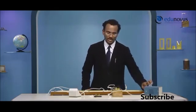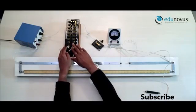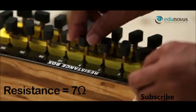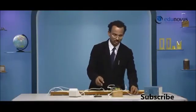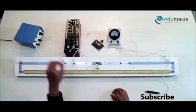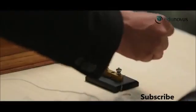Let's check our circuit first. Before I switch on the battery eliminator, I should include some resistance in the resistance box. So let me include 7 ohm resistance. I do that by pulling out the plug from 5 and 2 in the resistance box. Next, I will switch it on. Now to close the circuit, I will plug in the key.